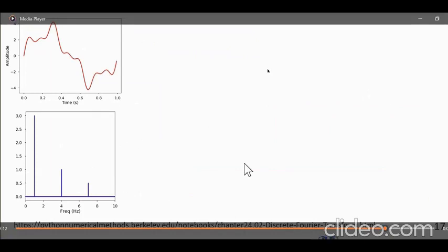So let's do a few things here. This kind of function is a periodic function. If you did an analysis of that, you will notice that it's the sum of 3 sine terms with different frequencies: 1 hertz, 4 hertz, and 7 hertz. This is called digital signal processing. In other words, you have a curve as a function of time history, and you break it up into its sinusoidal components. Now, obviously, this is periodic. It looks like it's periodic.